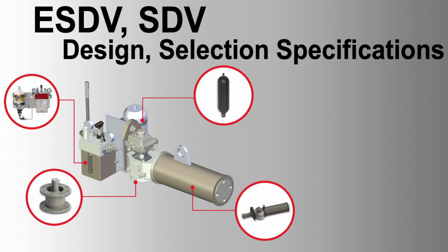3. Sealing: gaskets and seals, materials compatible to fluids such as Viton, PTFE, or graphite, ensuring leak-free performance. Instrumentation parts: 1. Limit switches. Function: indicate the open or closed position of the valve. Selection: explosion-proof and weatherproof models to ensure reliable operation in harsh environments. 2. Solenoid valves. Function: control the actuation of the valve, open-close, by converting electrical signals to pneumatic or hydraulic actions.